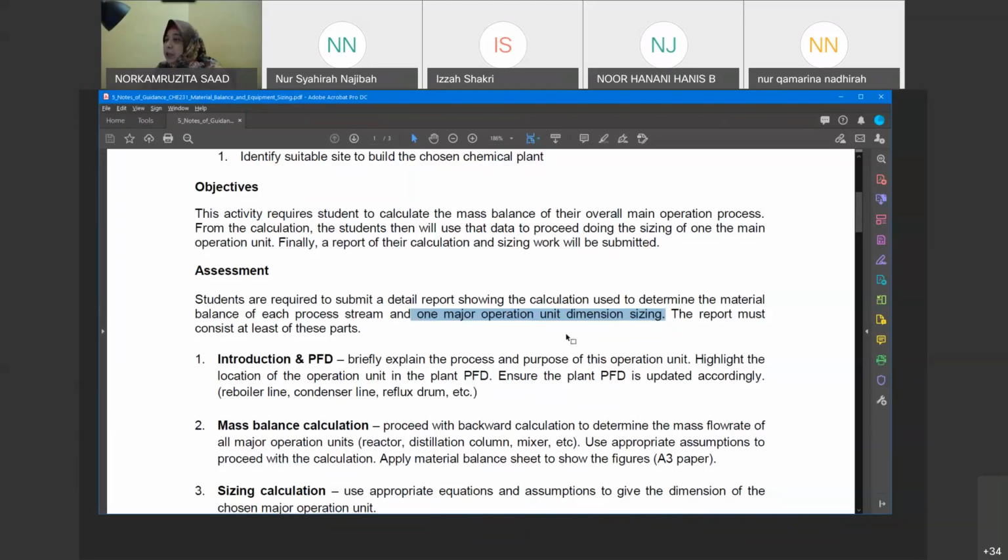So the purity that you decide is a design property that you would like to have. A reflux ratio is also a design that you're going to have. Even the inlet stream, which is the feed to your equipment or to your major operating unit, is also a control parameter. For distillation, the condition of your feed can also be designed, meaning that you can control the feed.